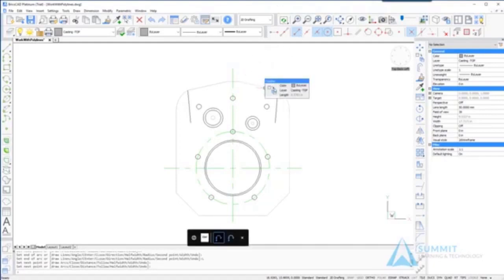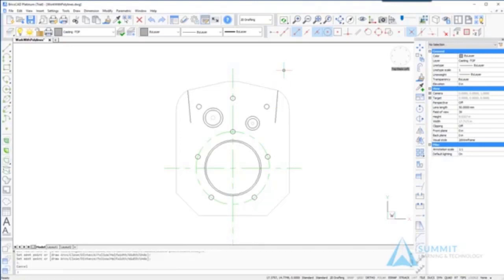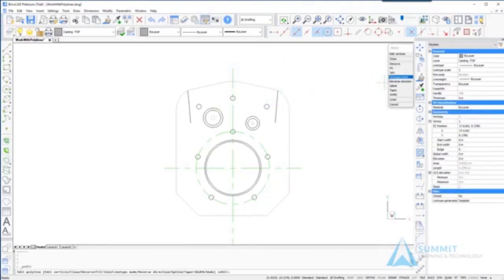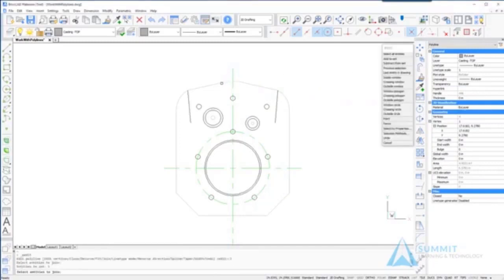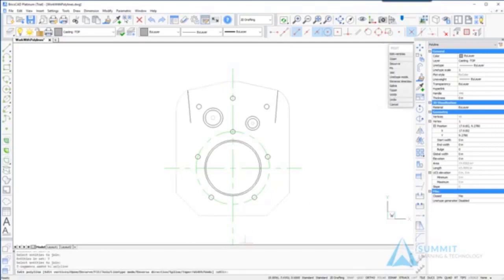Now hovering over this line, I can see on the quad cursor menu that it is indeed a polyline object. The next thing we want to do is double click this polyline. That's going to launch the pedit command, and then choosing join on the prompt menu and selecting the objects as shown here, and then pressing the right mouse button.